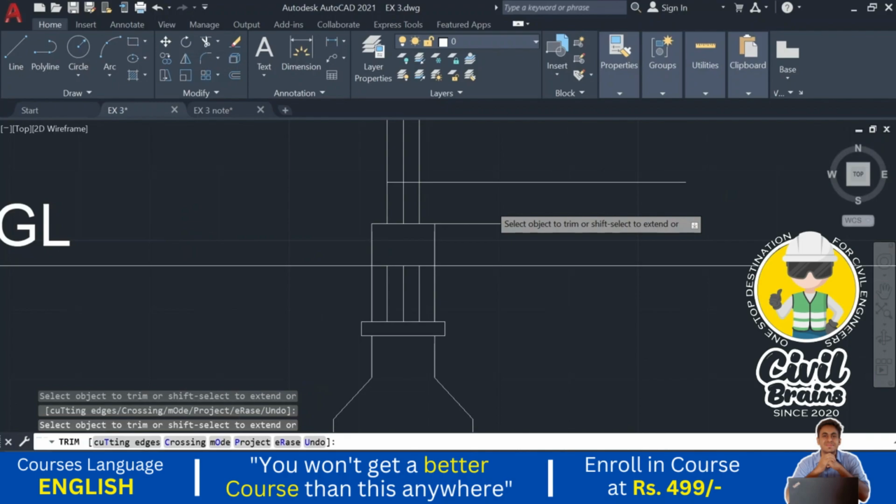I just trim the extra parts so that it will be easily visible. So here you can see, from ground level up to 1.5 meter this will be visible, and here this masonry structure is visible, and this will continue till the plinth level. Whatever our plinth level is, the same level I just continue here using the line command. All the wall masonry will go up to the plinth. At the plinth we are providing the coping or PCC, we can say.